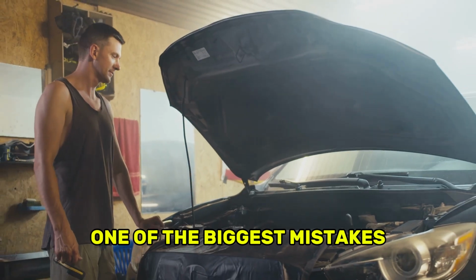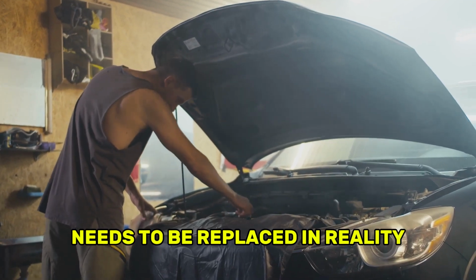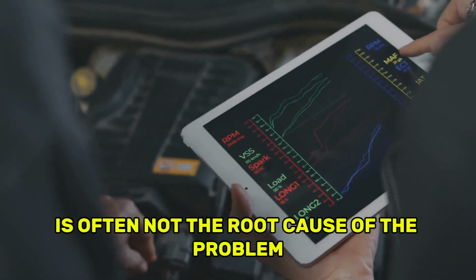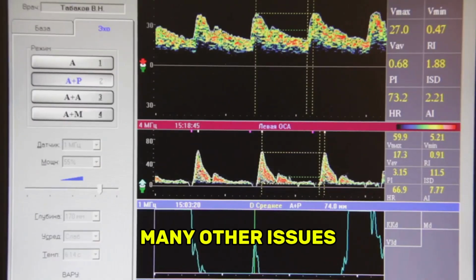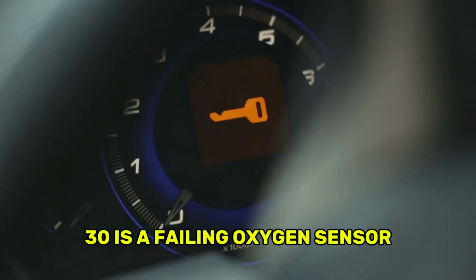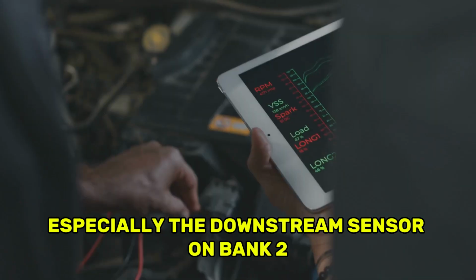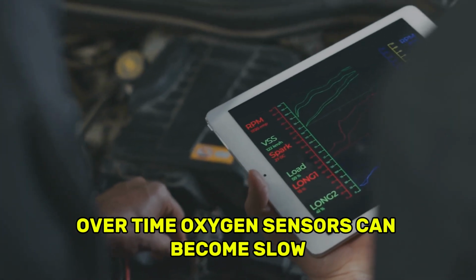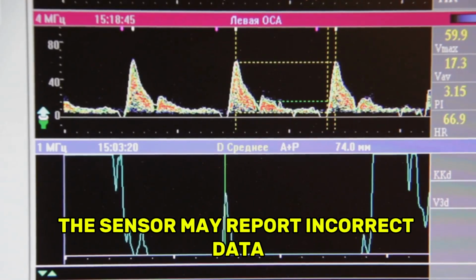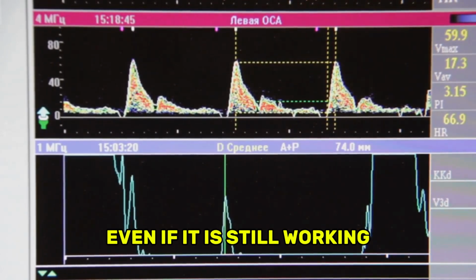One of the biggest mistakes people make is assuming that P0430 always means the catalytic converter needs to be replaced. In reality, the catalytic converter is often not the root cause of the problem. Many other issues can cause the sensor data to look incorrect. A very common cause of P0430 is a failing oxygen sensor, especially the downstream sensor on bank 2. Over time, oxygen sensors can become slow, contaminated, or biased. When this happens, the sensor may report incorrect data, making the converter appear inefficient even if it is still working.